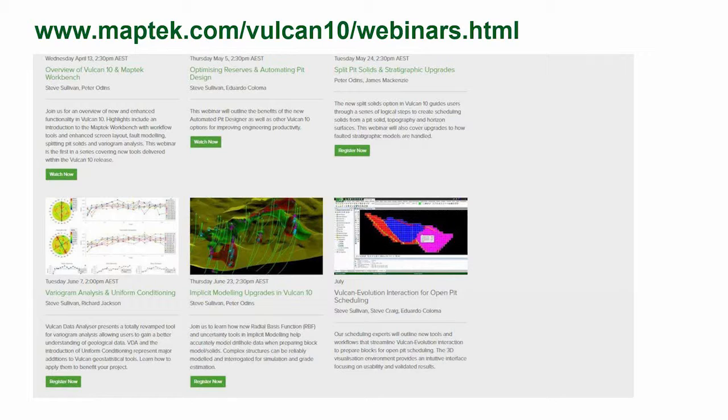Actually, we do have one more question here. One is saying, what else, in general terms, have you done in version 10 stratigraphically? So there are a range of other options I can very quickly talk about. I guess the first important one is that Vulcan 10 is coal log compliant for the geologists out there who want to make databases and coal borehole graphics and all things like that. It's been fully coal logged, so all the necessary database templates and geological dictionary codes and everything have been set up for you.